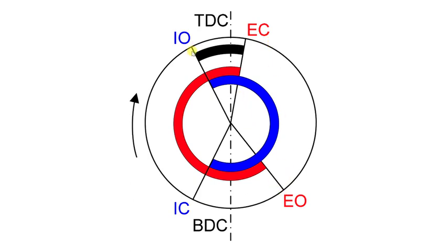What they're specifically pointing to along all of these four lines are the exact points where the valves open and close. So the air inlet valve opens at the exact point here where the line is, and the air inlet valve closes again where the line is here. But let me show you how you can read the diagram. So let's imagine that we've just finished a combustion cycle and we need to draw fresh air into the cylinder.